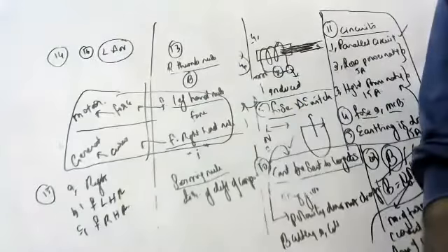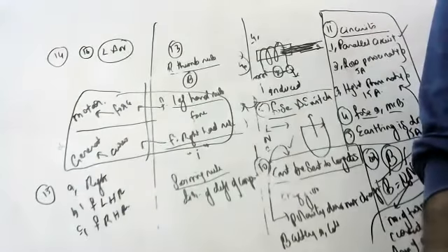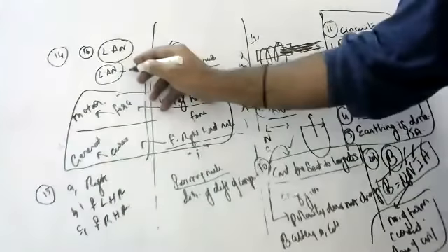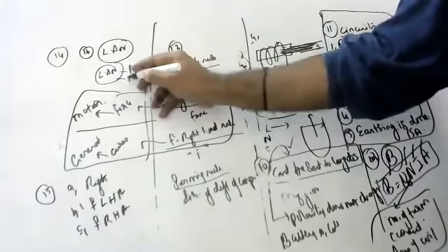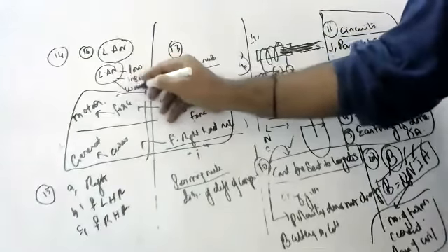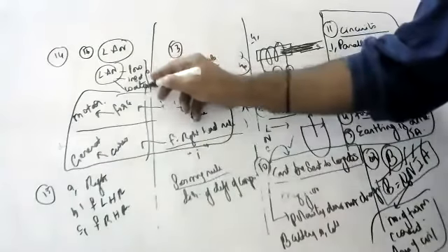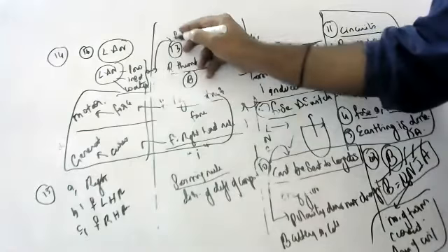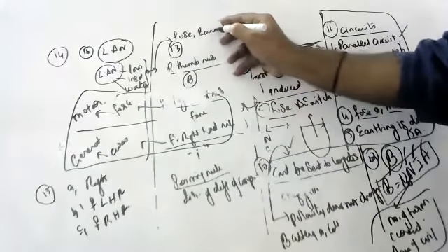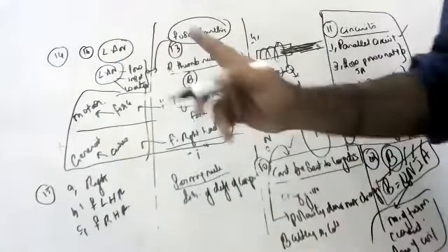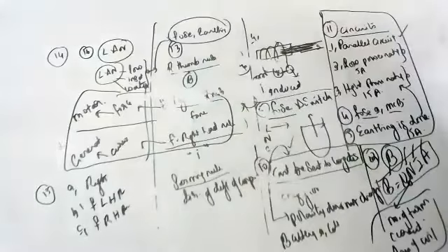Okay, children. The question is, state one condition which can lead to it. If live wire and neutral wire touch each other, under what conditions? It may be due to low quality wire, some insect bite, or it may be due to entry of water. And name a household device that acts as a safety measure for it. The safety measures are fuse and earthing. What are the safety measures for short circuiting and overloading? Fuse and earthing. How to avoid it is by using good quality wires.